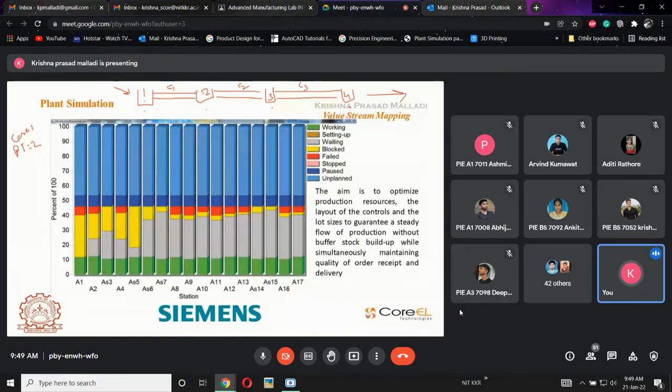In this, what will be happening? The 49th part was processed, and the 49th part is going to enter the third machine. Here the 48th part was processed, here the 47th was processed, which means every machine is having a part, and every 2 minutes there is a new part entering here. There will be no waiting and no blocking in this case one.